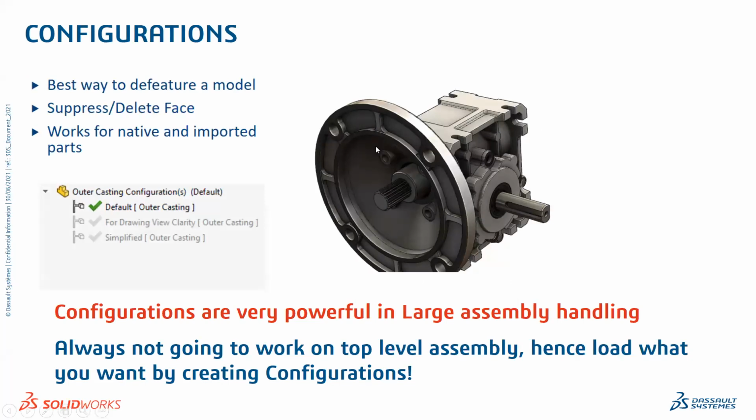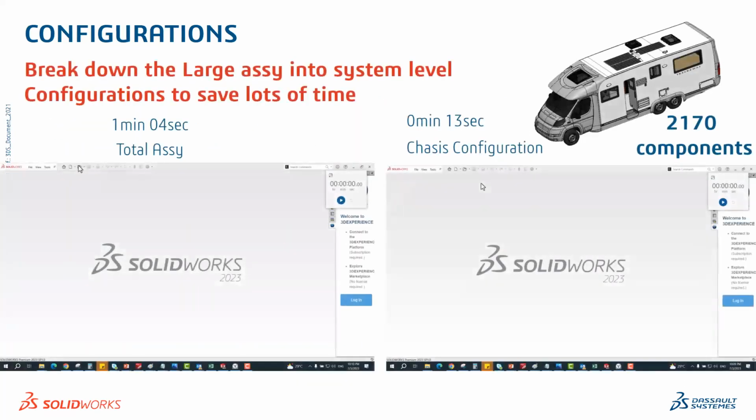Configurations, use configurations instead. When you are importing models with lots of features, try to optimize using the Defeature tool, or suppress or delete unwanted faces. This works very well with imported models. Configurations are very powerful in large assembly handling, and we are not always going to use the top level assemblies. Hence, use the configurations effectively.